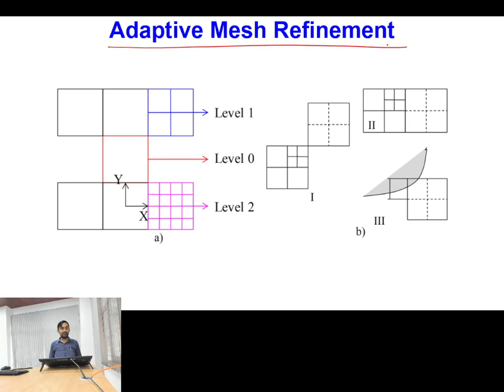Typically, we can instruct our mesh generating algorithm that only the cells which contain a gradient of the volume fraction will have fine mesh, and away from these cells we can have coarse mesh.